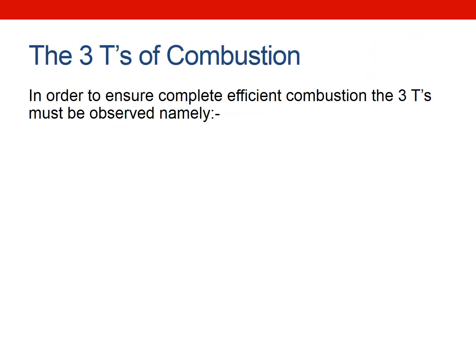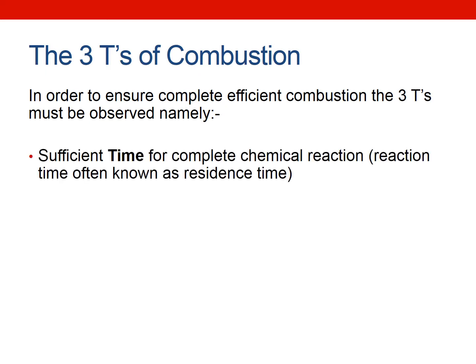So I just want to put this one in. We are talking about combustion, and once you get your fuel into the engine, what's really promoting how the fuel combusts with the air is what's called the 3 T's of combustion. If you have these 3 T's, then hopefully you have complete and efficient combustion, and they are time. So you need sufficient time for the chemical reaction to occur.